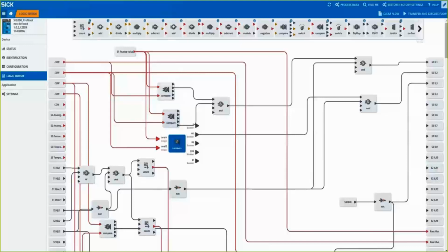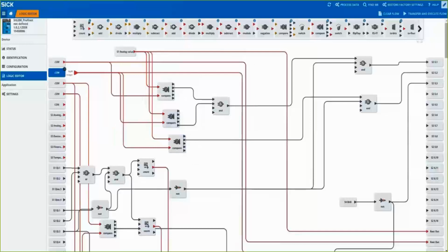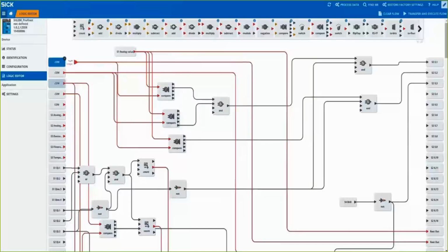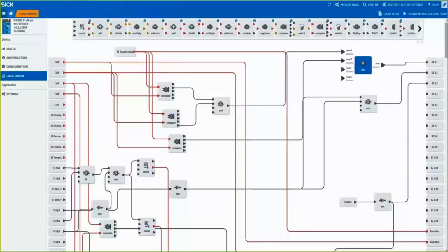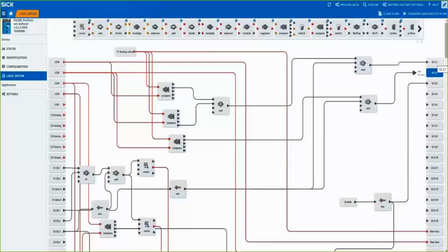So we've got the analog value coming in from the inductive sensor, and there's 3 compare blocks there. And basically we are seeing what the value is, and depending where it falls within those compare blocks, we will give an output. And in this case, we're saying that it's either between value A and value B, and that we would say is an acceptable level. And if it's below another value, we would say that was an unacceptable level, implying that perhaps the chain had drifted out of position and was no longer giving a value that satisfies the conditions that we've laid out.